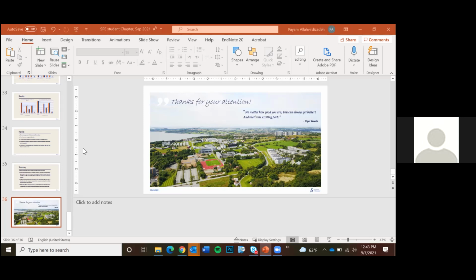Could you please give the composition of the cement? Is it like well-based cement? It's Class G Portland cement that I use, which is very common. And are you planning in your research to change the chemistry? No, I didn't, but that could be a possible way to try with different chemistry, different combinations. Also, I used neat Class G. You can also add additives, dispersers, or retarding additives, this kind of stuff. I didn't use any of it.